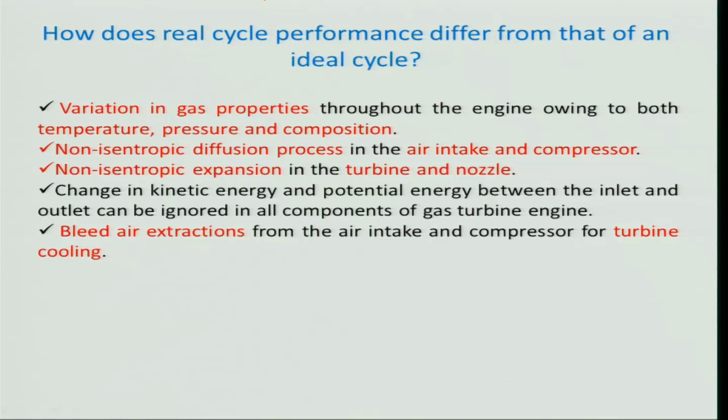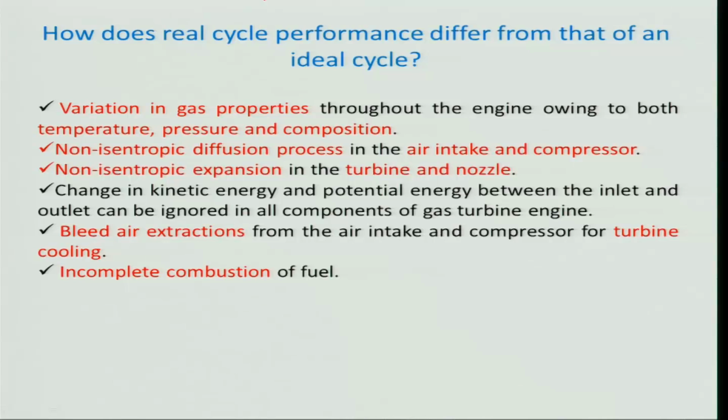Problem due to what? Problem due to surging, flow separations and other things due to adverse pressure gradient in the air intake and compression. Those problems, you will now be using for cooling the turbine. It is a win-win situation, right. That is the kind of thing engineers have developed, how to overcome a problem and at the same time solve another problem.